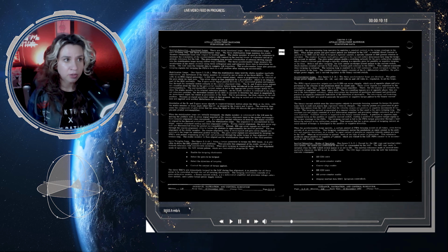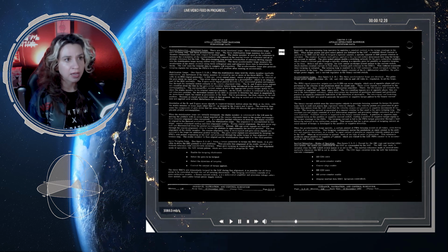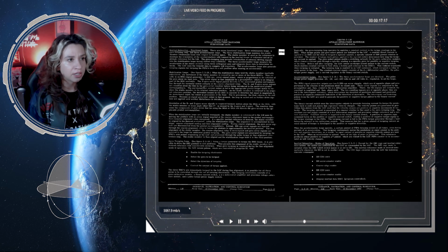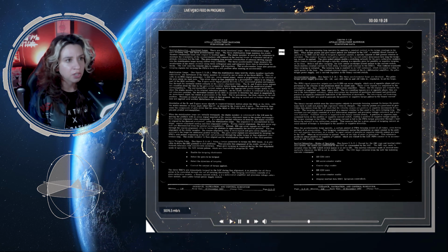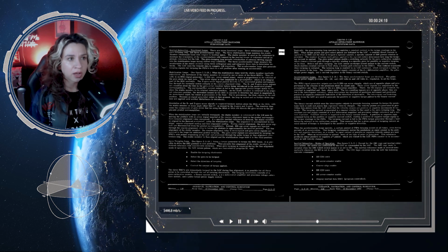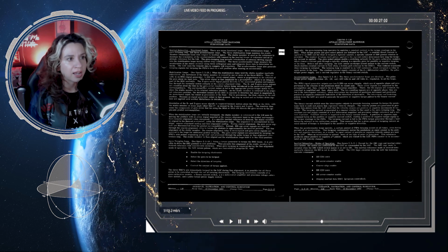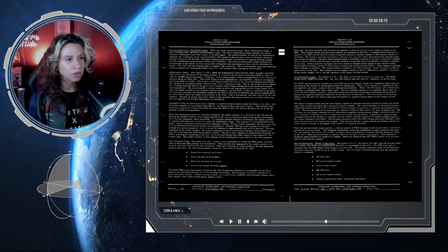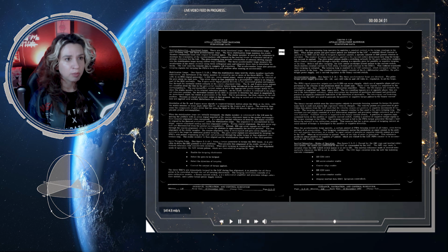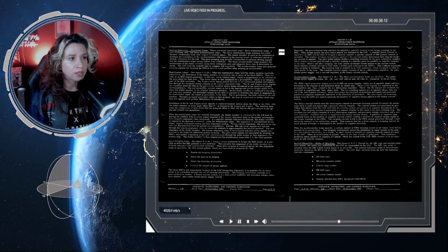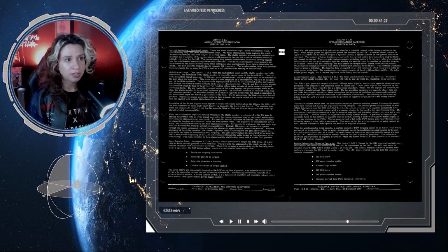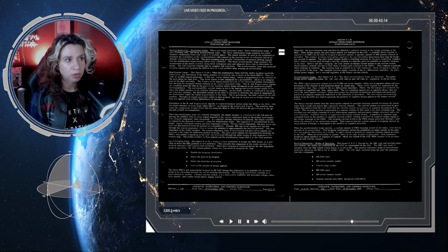Basically, the gyro torquing loop operates by applying a constant current to the torque winding in the IRIG. When torque pulses and gyro-select pulses are initiated by the LGC, a constant direct current is applied to the IRIG, and the float is torqued a specific amount. A specific amount of IMU gimbal rotation is provided.